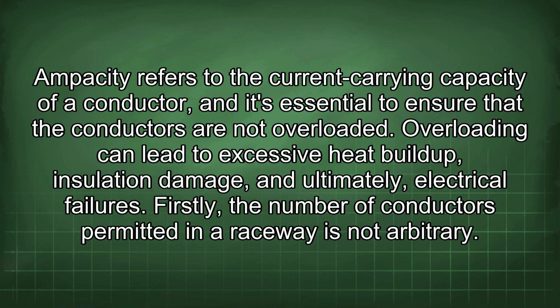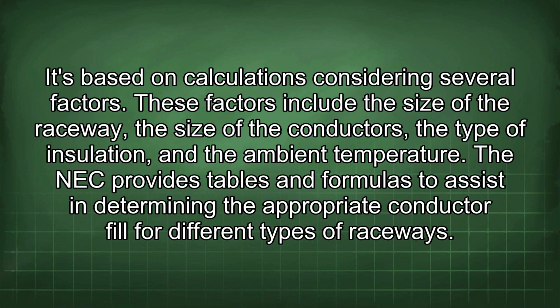Firstly, the number of conductors permitted in a raceway is not arbitrary. It's based on calculations considering several factors. These factors include the size of the raceway, the size of the conductors, the type of insulation, and the ambient temperature. The NEC provides tables and formulas to assist in determining the appropriate conductor fill for different types of raceways.